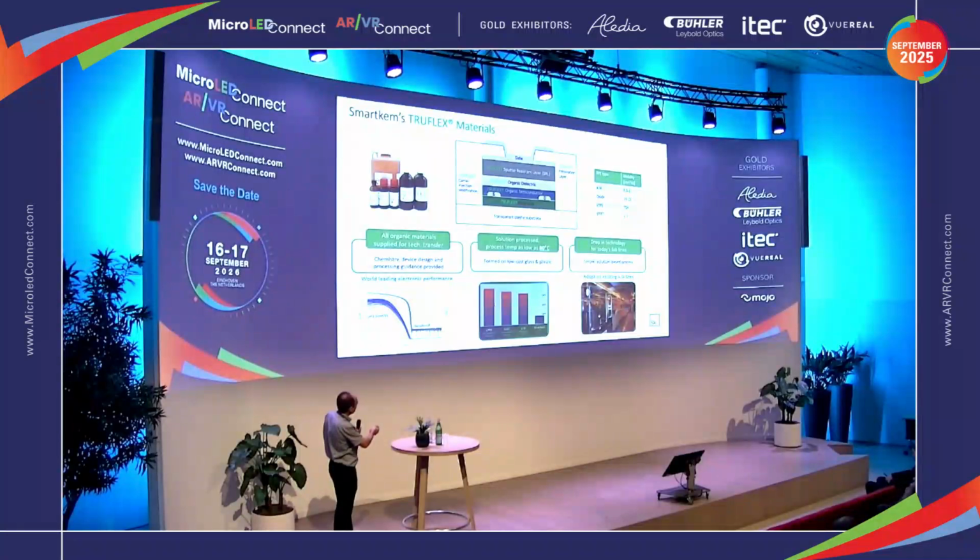LTPS is shown here as over 300, but typically it can be over 450 degrees C. This causes substrates to become yellow through the heat treatment process. Even colorless polyimide doesn't survive completely colorless after the processing. That's why people are interested in OTFT for making very transparent, flexible displays.